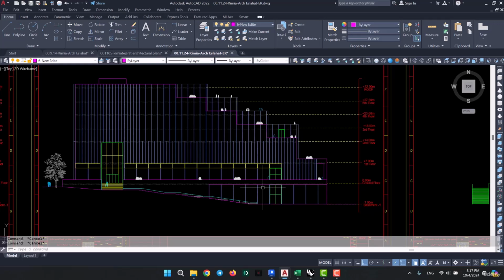Because you see, when we model our projects using the BIM methods, we would have to double check every single thing and make sure it's correct. Generally, I would have to import this elevation in Revit and first see if the elevation I have drawn for my plans in Revit is exactly coordinated with this one or not. Maybe the position of the mullions are different, and if the drawing and the elevation are contradicting, I would have to report it. Essentially, this is how BIM works. You will have to report all the clashes and any misalignments in the project, and let your client know before proceeding. That way, the project will go further faster, and it would even cost less to model and construct.